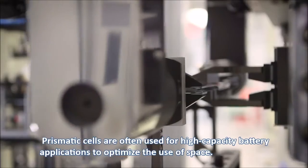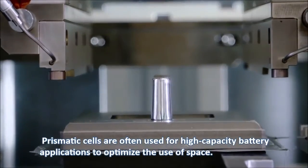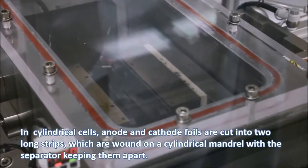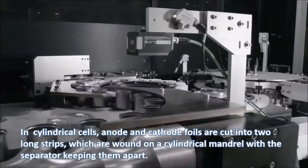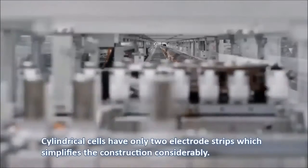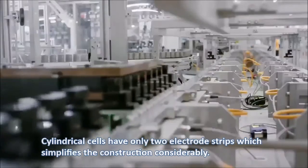Prismatic cells are often used for high-capacity battery applications to optimize the use of space. In cylindrical cells, anode and cathode foils are cut into 2 long strips, which are wound on a cylindrical mandrel, with a separator keeping them apart. Cylindrical cells have only 2 electrode strips, which simplifies the construction considerably.